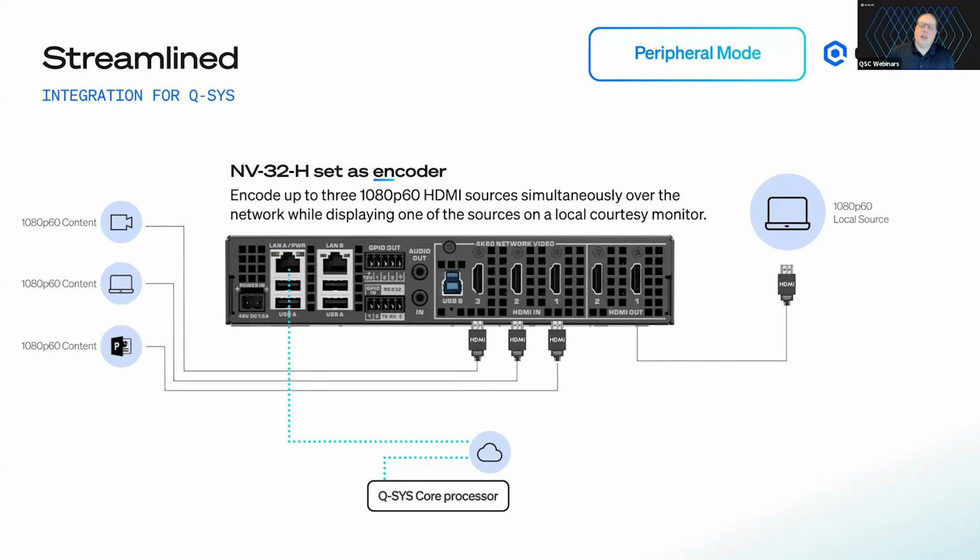90 watts. Yeah, it's a hungry little guy. So it's not going to be a full 90 watts, but we need to have 90 watts available for the unit on startup. As it's running, it'll be closer to about 70 watts. But yeah, we need to have PoE++ on startup, thus the 48 volt 1.5 amp if you're powering it locally.